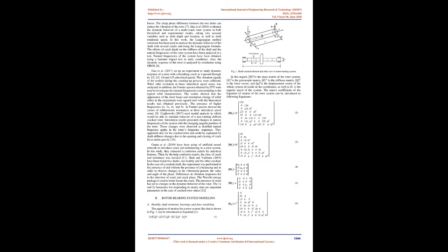Furthermore, a new finite element method has been introduced to model the breathing behavior of the crack. Then, the short-term dynamic response of the rotor system was analyzed using the Fourier transform. The ability of the short-time Fourier transform to detect small cracks was studied in the case of transient response. 6.